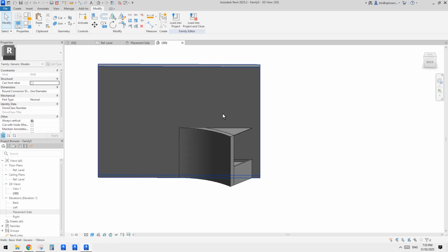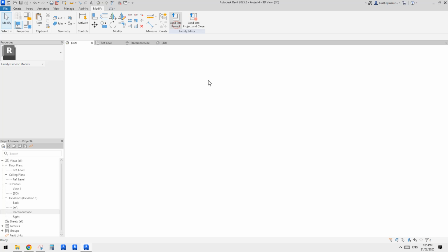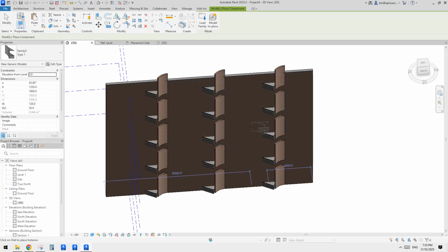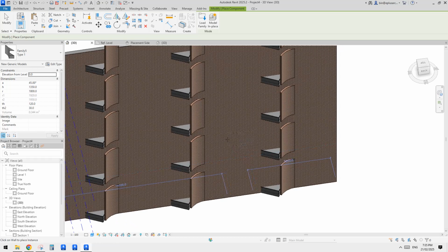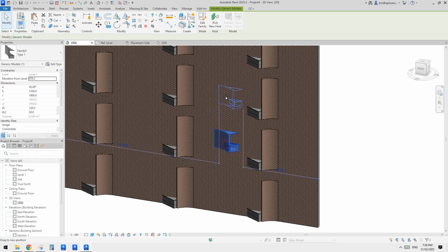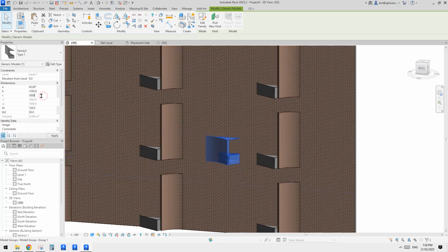And then we can place this one onto a wall. So let's load this one into this. Oh, hang on, what's going on? Oh, yeah. Don't worry. Escape. So see, now you can very easily place it onto this wall, right? So you can adjust the height, and I mean the level, you can use the level. I want it to be level 1 with 0 offset. That's it. I want this one to be 3 meter high, right?